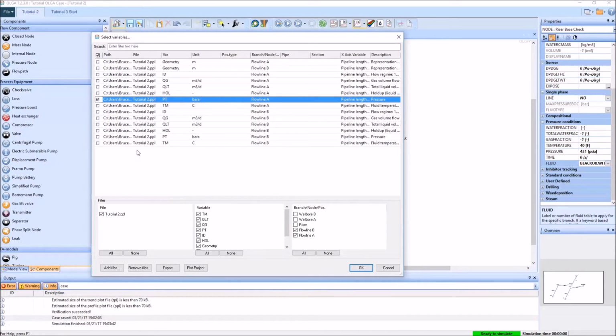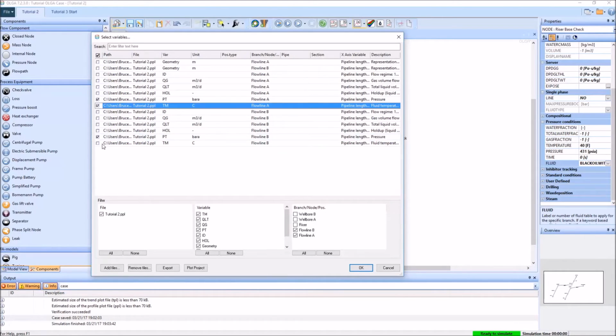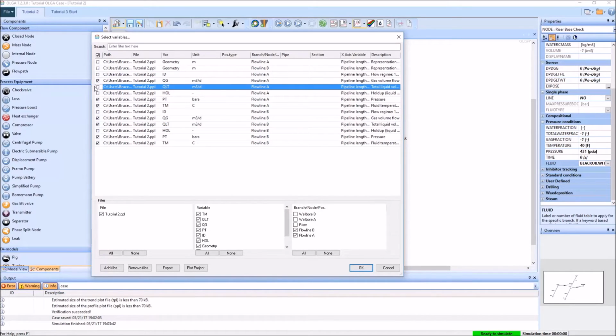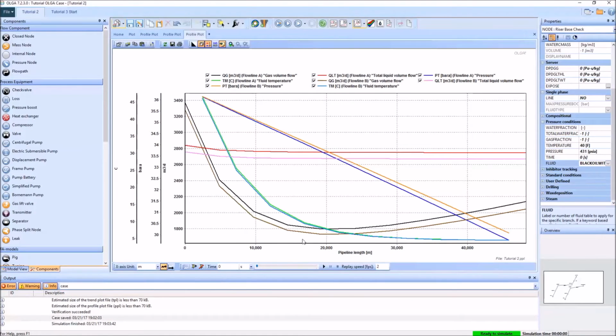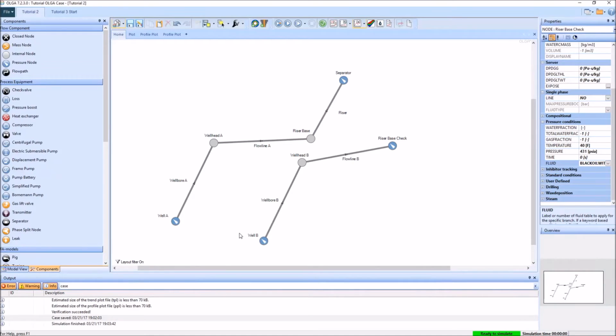So let's take a look at the pressure, temperature, and our flow rate. So we create this plot, and you can see that these curves lie more or less on top of each other. So this sort of similarity is fairly encouraging. It seems to suggest that things have gone well in our copy-paste process. And what we can do now is to actually begin to modify this second section of simulation here in order to better represent our reservoir B.